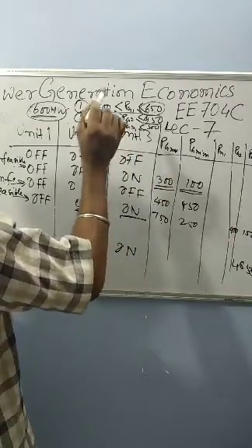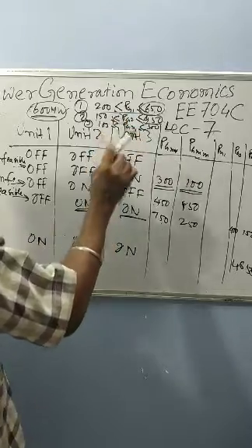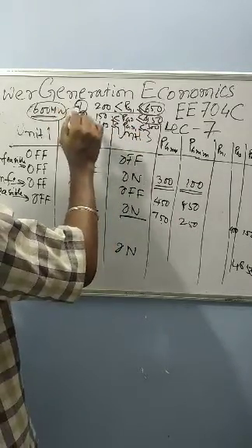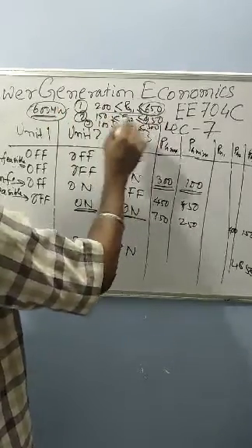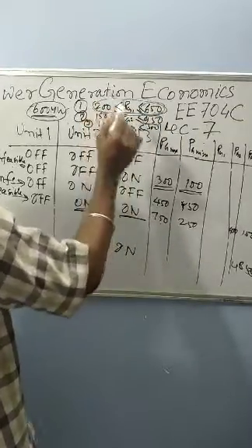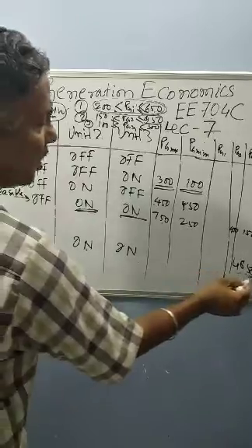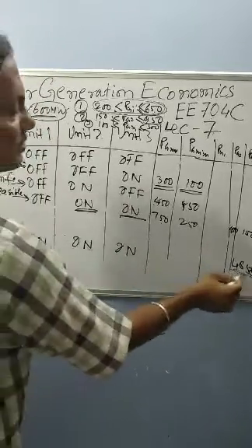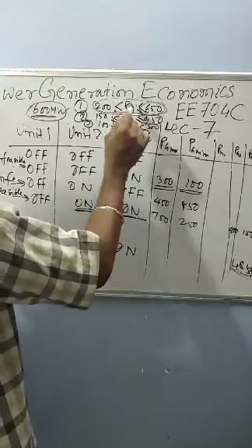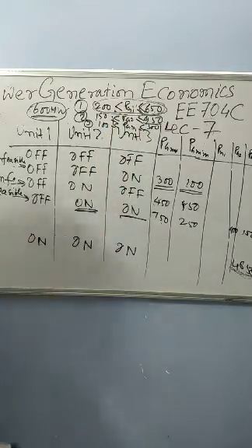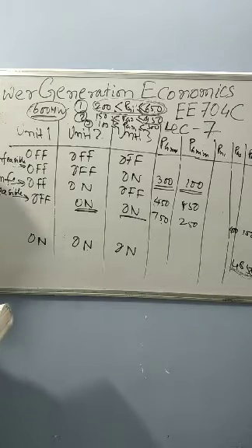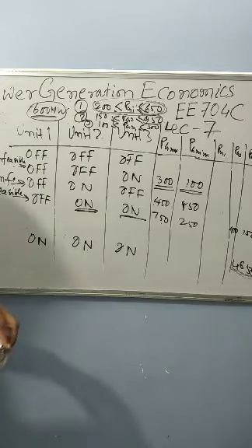So it is most economical under unit commitment to operate this unit, because this satisfies the load and the efficiency will be maximum. Though the cost is minimum if I run all the 3 units, still I have to operate the first unit because the efficiency will be maximum.